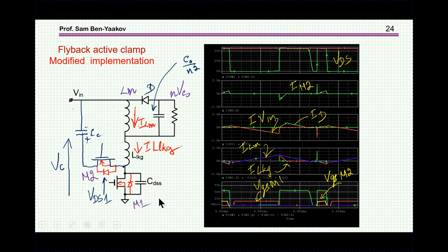Now the disadvantage here is that we are sort of leaving alone the drain voltage after the current goes this way, leaving it by itself, and there might be some oscillations, as we see here. So this is not a very nice thing, and this is why this method has not really been adopted.